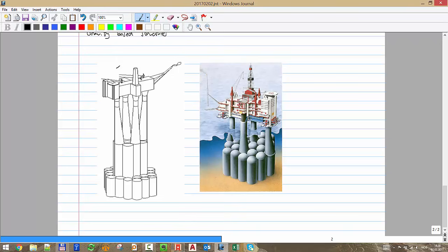Norway had a very strong concrete industry, so they decided to use all of this knowledge and expertise to build these big structures. Okay, and the thing is that they stand by themselves, by their own weight, but they have a system that is called suction anchor. Where it's an empty chamber where you have the soil, and then you drain out the air and you make some kind of suction cup effect. And that's how you also keep it in place. That helps on top of the weight to keep it in place. Okay, suction anchor.